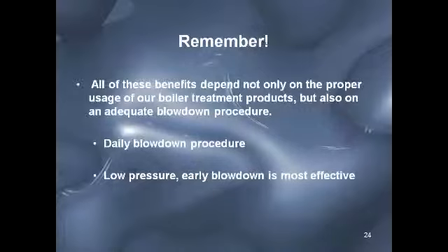It's very important to remember that all of these benefits depend not only on the proper usage of boiler treatment products, but also on an adequate blowdown procedure. After the boiler treatment precipitates the hardness and impurities from the boiler water, this unwanted material must be removed daily by blowing down the boiler.